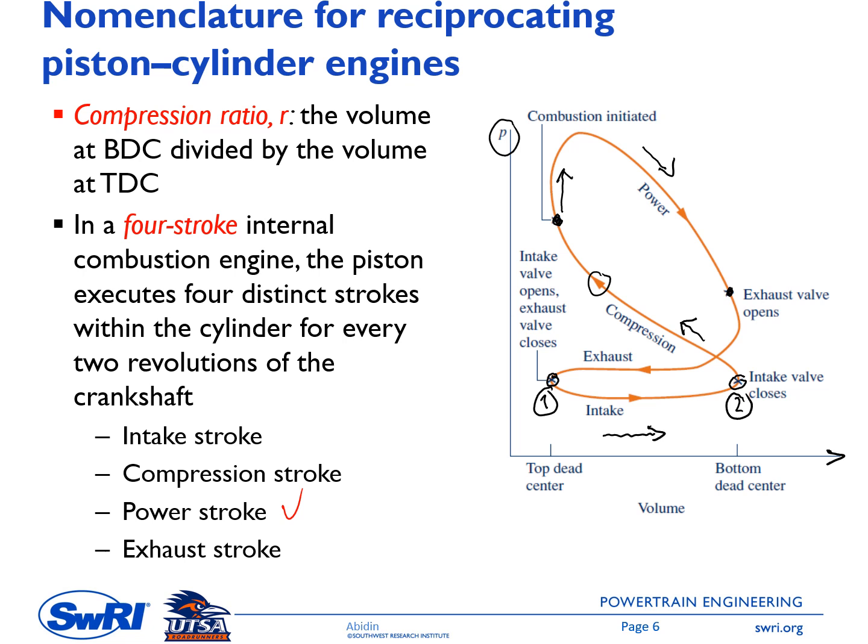Okay, and then the piston moves up again, going to the left. It means the cylinder chamber volume decreases, and the last process here is called the exhaust stroke. So we have point 1, 2. I can put here when this at top center is point 3, and then somewhere here is point 4. So this is the actual PV diagram of an engine.